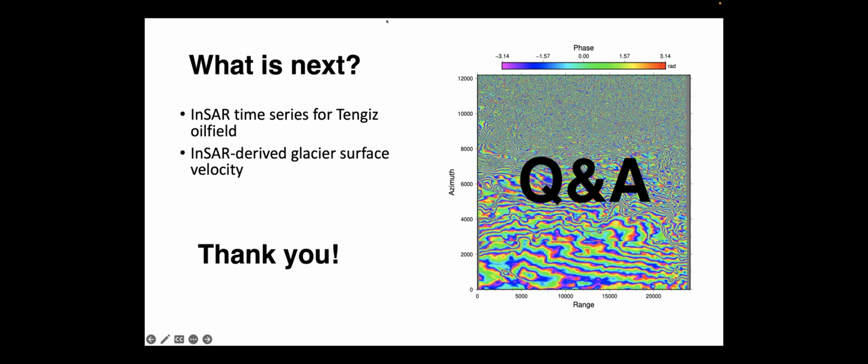But my take on this is actually it could be the ice moving, because these interferograms are not usually very sensitive to topography. So you could try a better DEM, but this could actually be ice motion. Yeah, but SRTM probably doesn't cover this far, right? Because SRTM only covers from positive 60 to negative 60 degrees. Yeah, there is no data for this latitude. So probably his processing does not have the DEM removed.